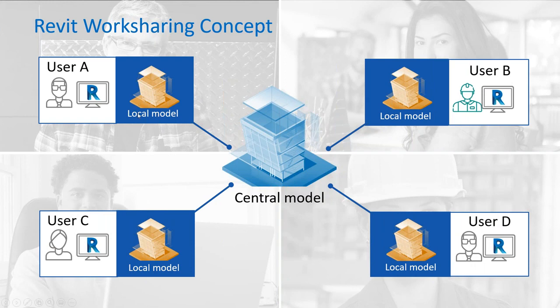And again, this is an introduction session, so I'm not going to spend too much time on the actual setup, but I like to think of this as sort of Outlook and Exchange. You all have your own email box, and there's an Exchange server, for instance, within the company. That's where you get your emails from, and that's what you're sending them to. That's sort of the same concept, not entirely the same, between a local model and the central model. Everyone is going to upload their changes into that central model.